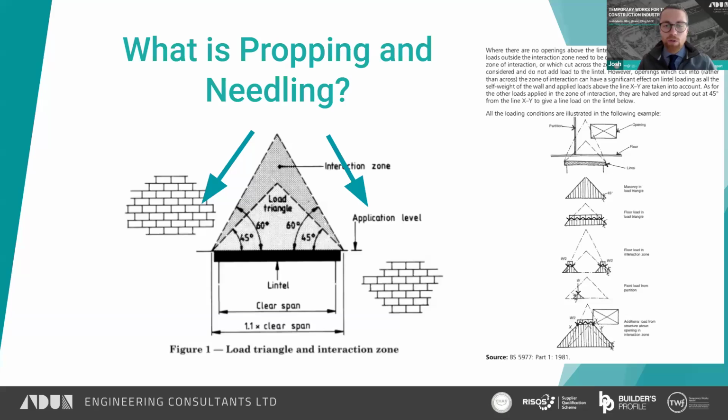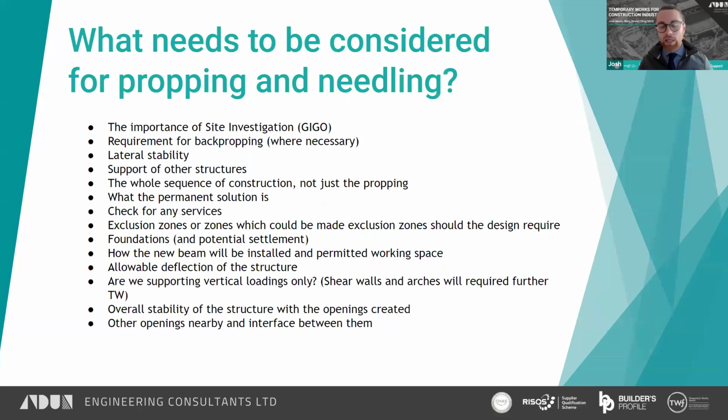So for larger openings, or openings where there's not enough masonry around to support and enable this mechanism, in those kinds of areas this method doesn't really apply. In which case, the full loading above the opening should then be taken and not that 45-degree loading type shown here. And it's worth noting that this is because of the arching effect, which is why very small openings for services or ducts don't usually require any support. And when you start to get to larger openings, say above half a metre or so, some form of support may be necessary.